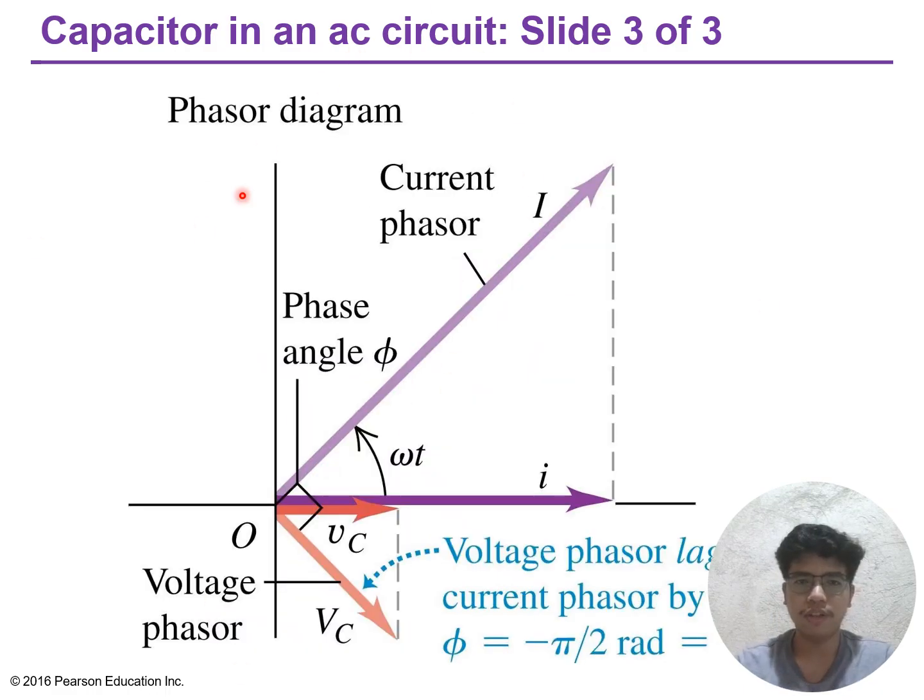Next, this shows the voltage and current waveforms for a capacitor, with the current waveform leading the voltage waveform in time. The time domain waveforms illustrated here make it visually clear that the current leads the voltage by 90 degrees in a capacitive circuit. The current waveform reaches its peak and crosses zero 1/4 cycle before the voltage waveform, demonstrating the current leading voltage temporally on the plot.